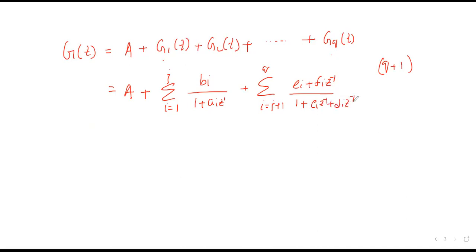Now, again, the question is how to represent them. Okay, so as we already said, the denominator is going to be the feedback, and how many delay elements are required here? Only one. So one delay element, z^-1, then X is coming as the input to the summing junction that is giving you H(z).